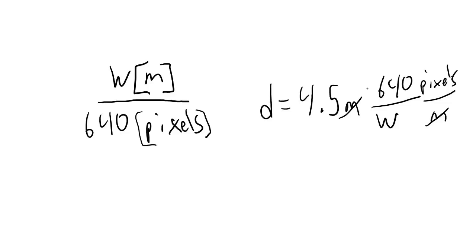Next, I need to have the average V. V, remember, is in units of pixels per second. This doesn't have to be exact. In other words, if a car is driving above or below the speed limit, we probably won't miss it if we assume a V of being the speed limit. However, this does do a good job of helping the camera to ignore input that is not relevant. For example, the speed of a pedestrian walking along the street is much less than the speed of the car driving, and so setting up my delta t with this V assumed will help to allow us to ignore pedestrians.